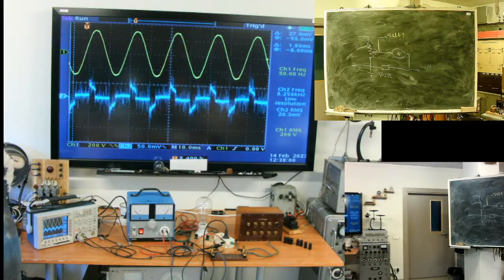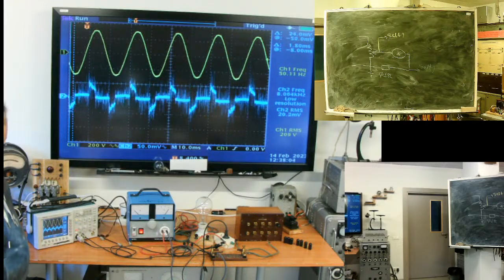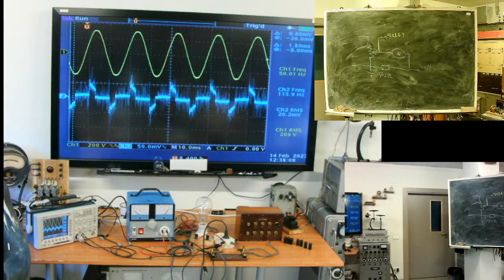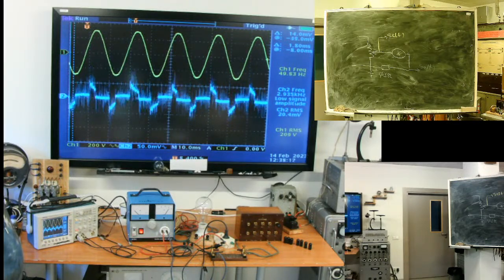It's harmonic, yeah? It's a nice sign. Why? It's a noise from the PWM converter of this power supply. It's a commutation noise from the PWM converter. If everything works well, I'll show you what's inside, if you have time.